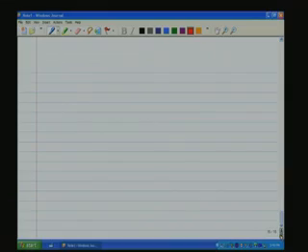You should know that the battery IV characteristics that we just saw is more of a general nature. The exact IV characteristic will differ from battery to battery, from type of battery to type of battery, from manufacturer to manufacturer, from ampere rating to ampere rating, and so on and so forth. So you should actually take the IV characteristic data from the manufacturer's data sheet for much more specific details.